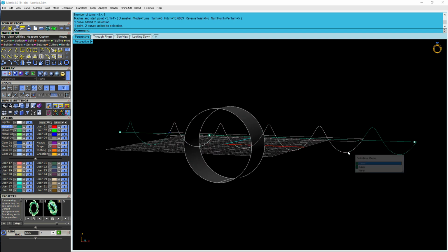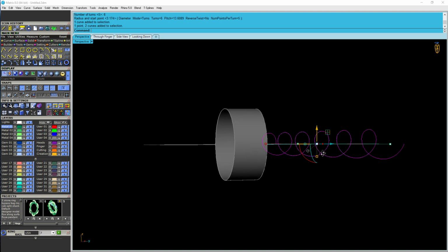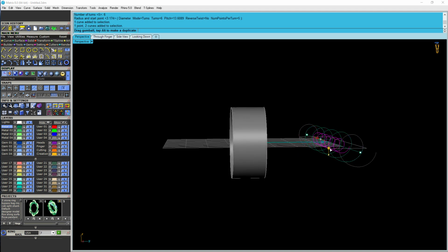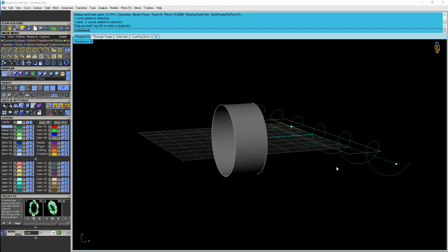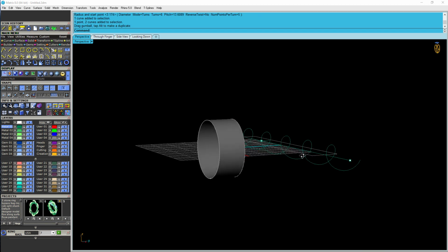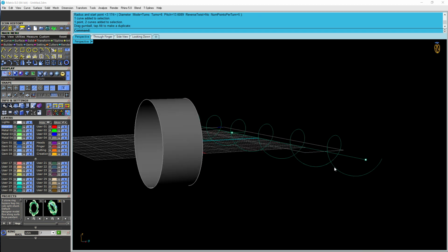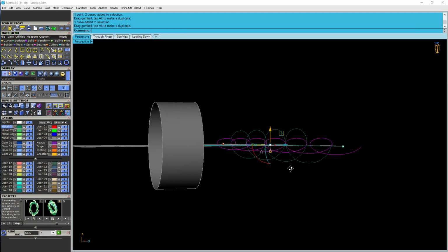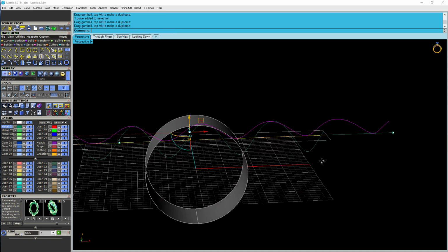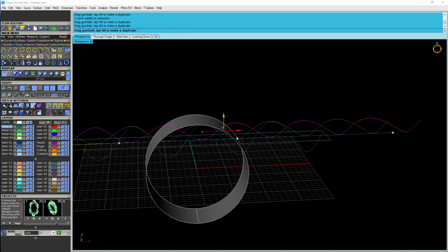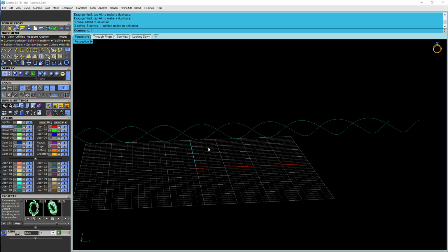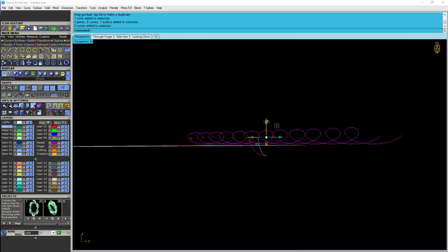And if you're doing a standard twist, now this is the same kind of approach you would do. Is you would start with the helix. You could scale it and adjust it how you need, but that there is going to give you that twist look. And I'll just kind of give you an example real quick. If you bring that forward, let me right click and let's type in pipe.